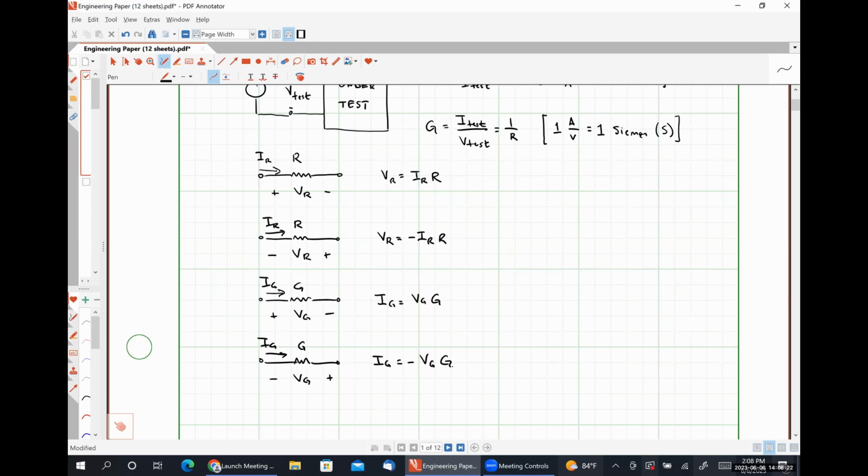Okay, so the overwhelming majority of the time, particularly in this class, it's going to be easier on you if you effectively neglect the concept of conductance entirely. Anytime you see a conductance, which you'll know when it's listed as measured in Siemens, you simply take the reciprocal of that conductance value and then treat it as if it were a resistor, and then you can go on about your day. So I would argue that for the overwhelming majority of cases, and practically all of them in this class, simply treat your conductances like an equivalent resistance.